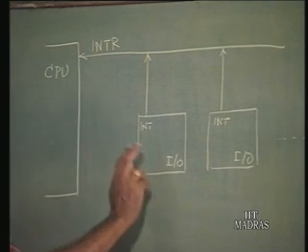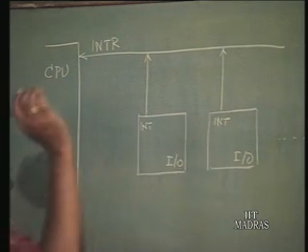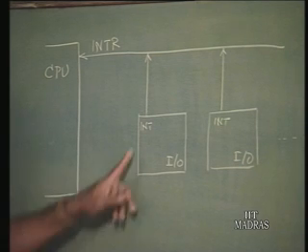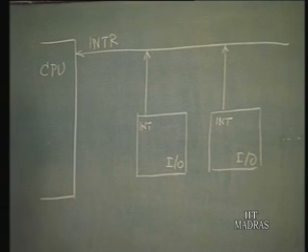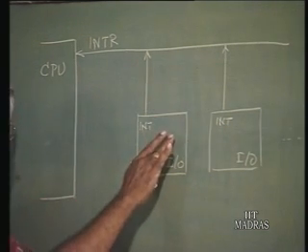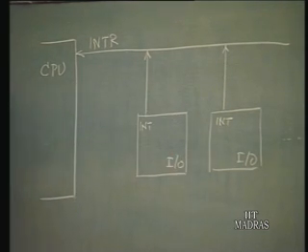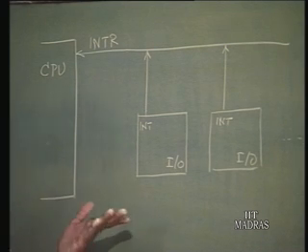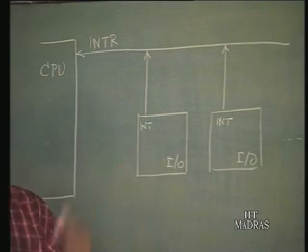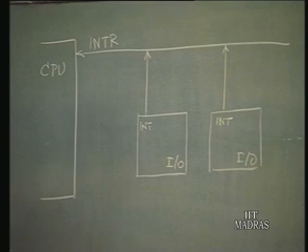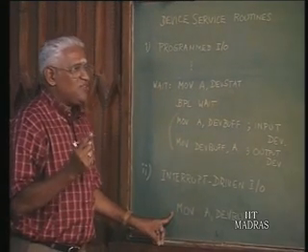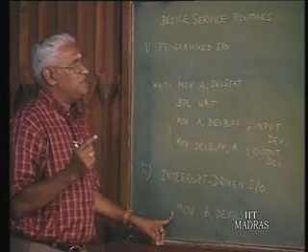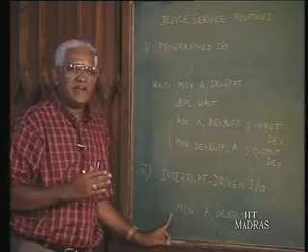So, what has been shown here is only how the device interrupts the CPU, that is all that is shown in this particular figure. The data bus will be connected to this, so that over that it will be moved, and the appropriate read write control signals, all those things will also be there. Not shown here, we will not bother about it. I hope you follow without any difficulty about that. So, the interrupt service routine, sometimes called just an interrupt program.